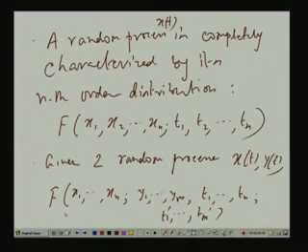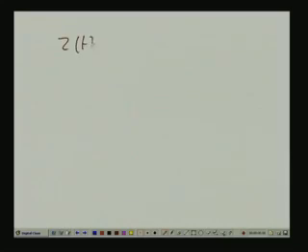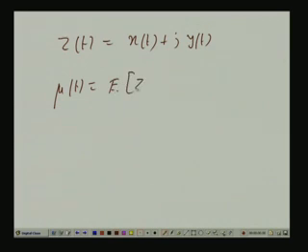In practice, we are more bothered by the moments, mean and autocorrelation or autocovariance. We have already seen it. We will just give the more generalized definition now, which is applicable to the case of complex valued processes. A complex valued process Zt means that at every point of time it takes some complex value. Okay. So, you can also view it as a summation of two waveforms. One is a real waveform, another waveform corresponds to the imaginary part. For this kind of process, mu t remains as before, E of Zt.